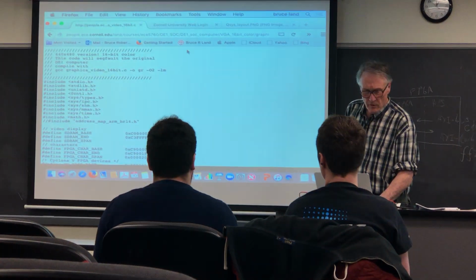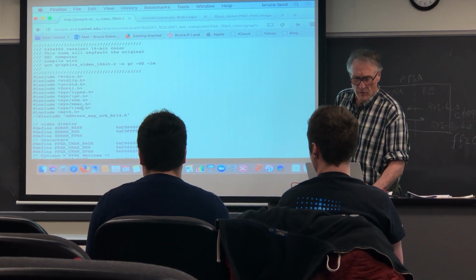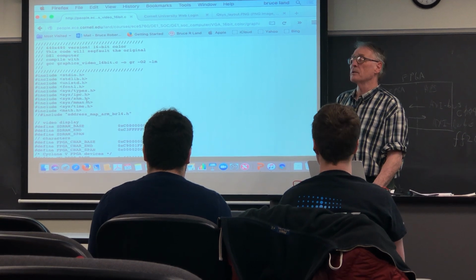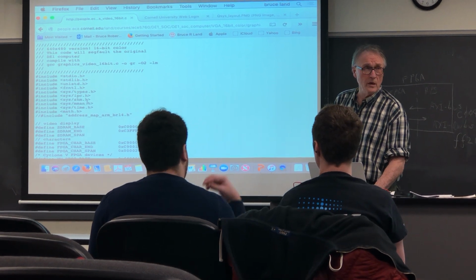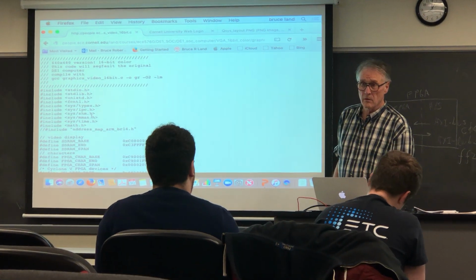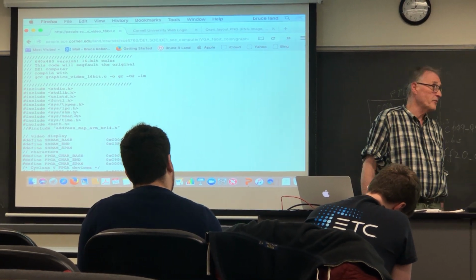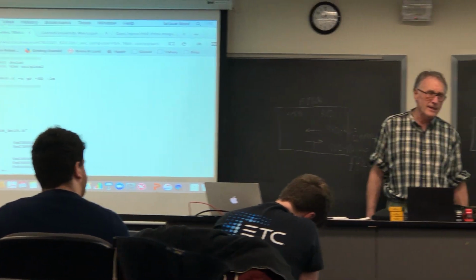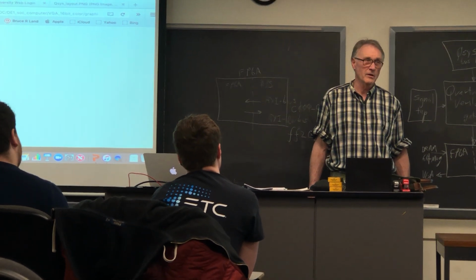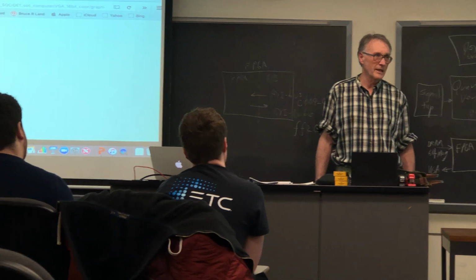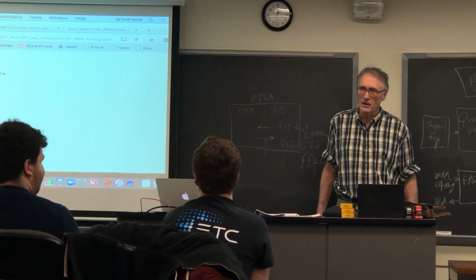But if you look at the HPS program, it's going to start out by doing the usual stuff of importing a bunch of libraries. And oh, you're going to compile this on the target HPS, by the way. The C compiler runs on the target HPS, yes. So then, how do we get the source code on the target HPS in the first place? Well, in Lab 1, it gives two suggestions. There's actually three ways to do it. One is, if you're completely insane, you edit directly on the SD card. Don't do that. First of all, SD cards lose data. Secondly, Vim is a terrifyingly awful editor, in my humble opinion.